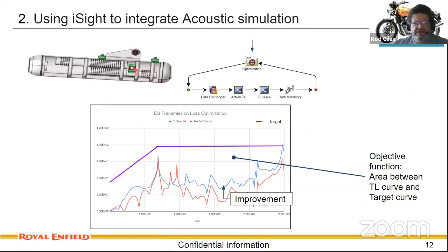So you can see here that we've got a series of holes inside the muffler in the tubes, and we can vary both the diameter of those holes and the pitch spacing of the holes, and completely automatically find the transmission loss for those parametric models.